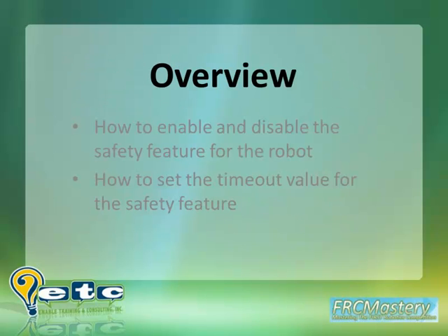In this tutorial, we will be having a look at the safety configuration VIs. These VIs are a replacement to previous year's Watchdog VIs, but their function is similar. We will be using the safety config VI to enable or disable the safety feature, and we will be learning how to set the timeout values for the safety feature as well.